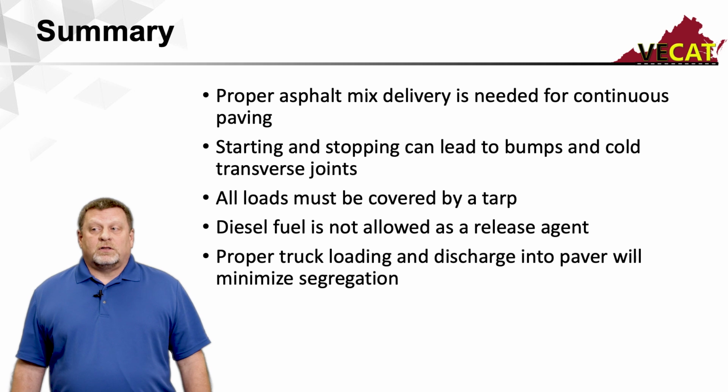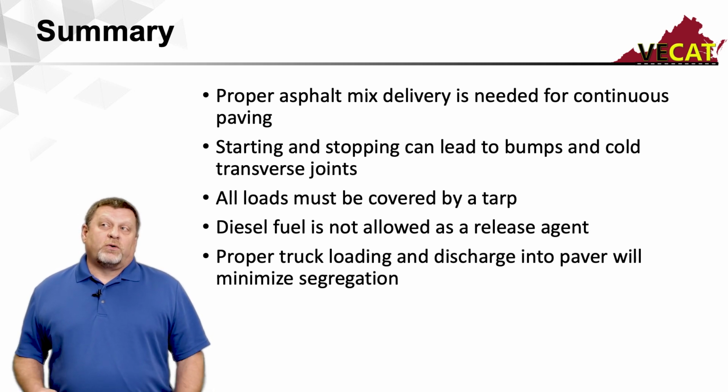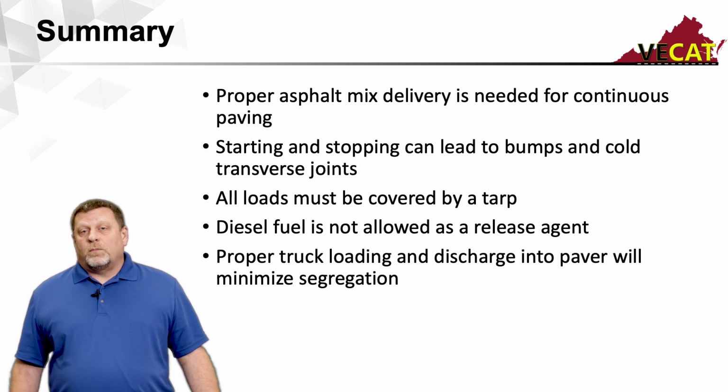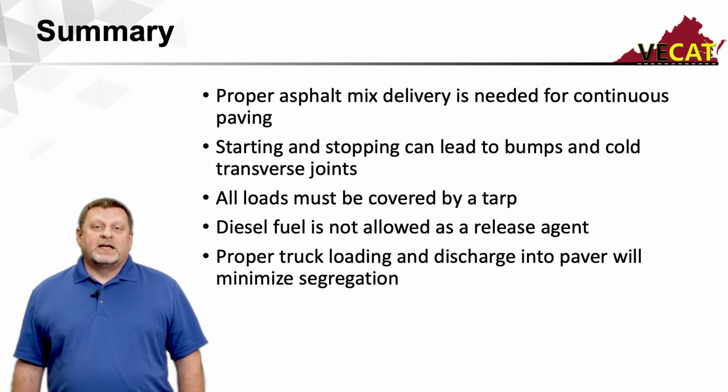And proper truck loading and discharge into the paver will minimize segregation. When we load the truck, we want to do multiple drops. The larger the gradation band, base mixes and the intermediate mixes are more prone to segregation than maybe a 9.5 surface mix. So it's important that we really pay close attention when we're running coarser type mixes. And again, dumping into the paver hopper or the MTV hopper, we want to make sure we raise that bed about a quarter of the way before we release the tailgate, so that mix moves in a solid mass into the hopper to prevent any of that segregation.